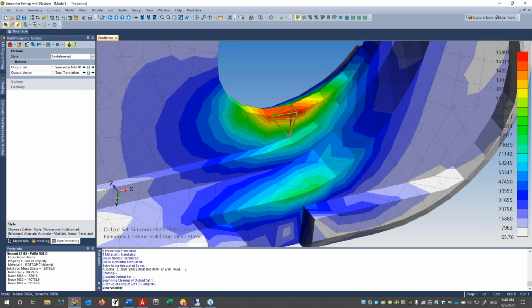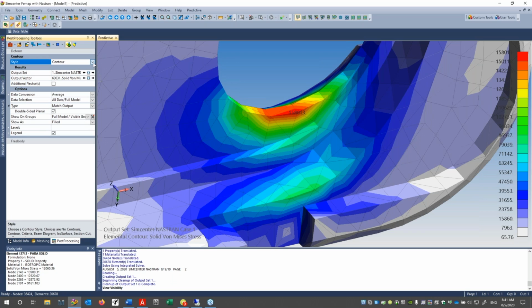And of course, the nodal point stresses are averaged with other elements, because elements computationally are solved as islands with their nodal stresses, and then they're dumped out, and the stresses at nodal points are averaged. So we see at the centroid we have 130, and at the corner points we have 160. So we have a delta of 30. So what we got, like a 20% work function going from 130 to 160. 20%, not bad. It's not 50%. Seems reasonable.